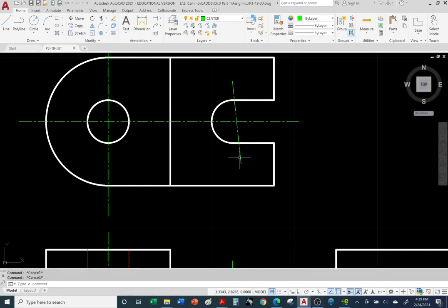Okay, so I'm going to use the grip, and try and make it vertical. I'm going to have to recreate it. Let me go ortho. So I'm having trouble recreating the vertical line. Okay, so I'll just have to recreate it over again. Hit escape. I can delete this. I'll just recreate it. If you have trouble like I just did, just start over, right? Recreate it again. So now I do have ortho on, so it's not going to create a crooked line. Okay, hit escape.